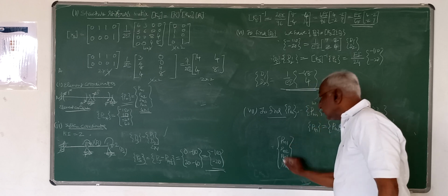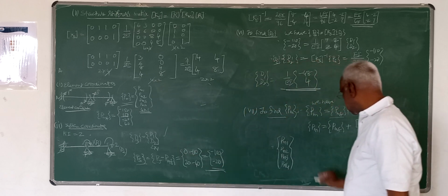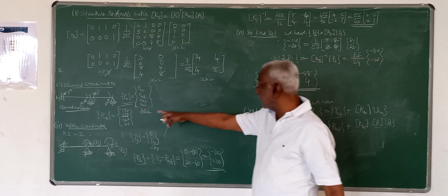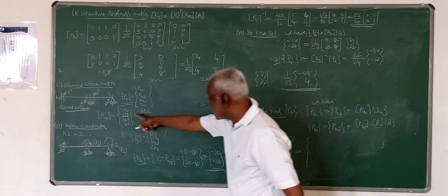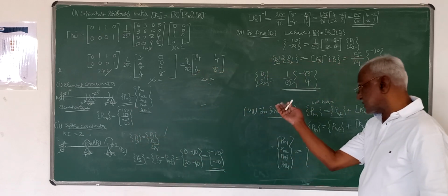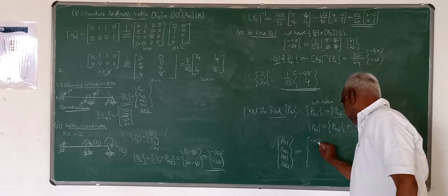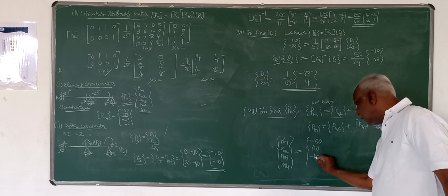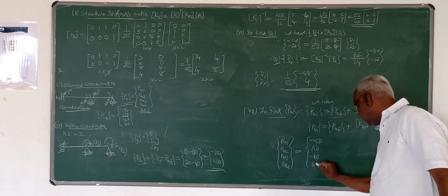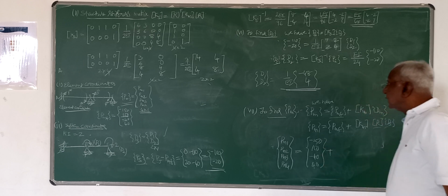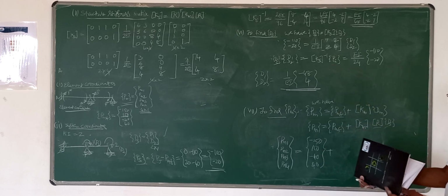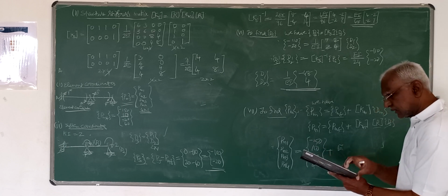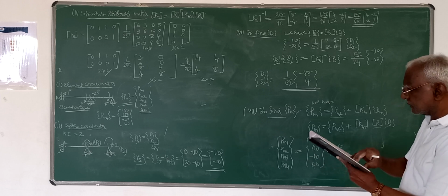Pm4. That is the fixed end actions, that is equal to PMF, that also you have determined in the first step. You have determined the fixed end actions, that is minus 150, plus 150, minus 40, then 40, plus 40. That is PMF plus Km. Km you have generated, that I have here, that is Km is nothing but